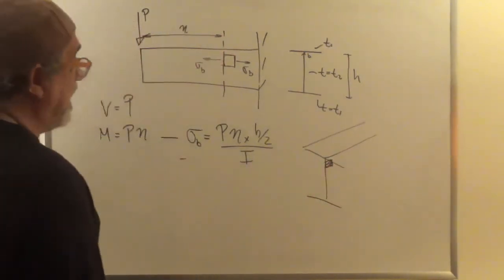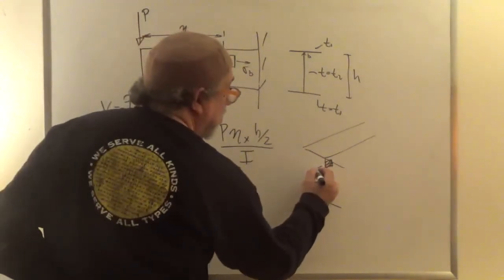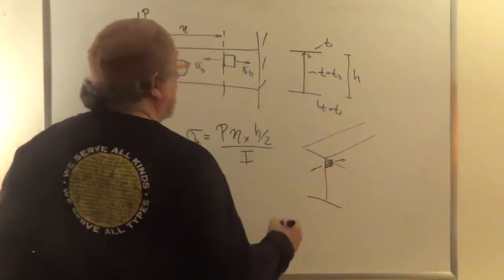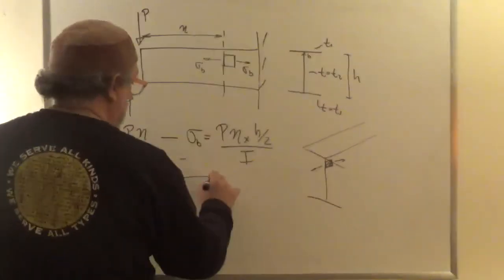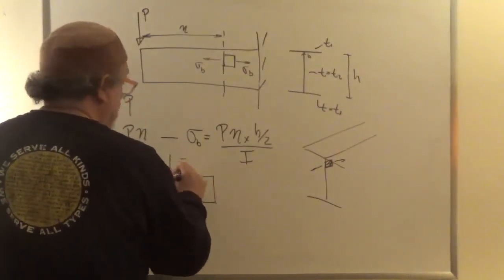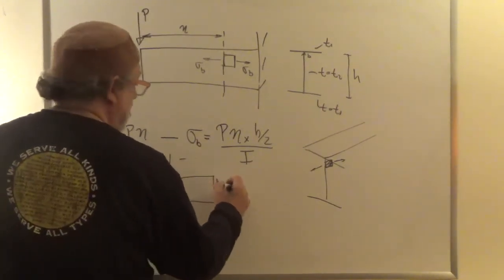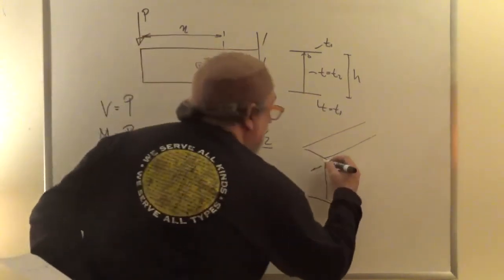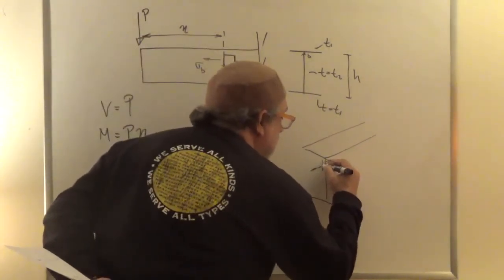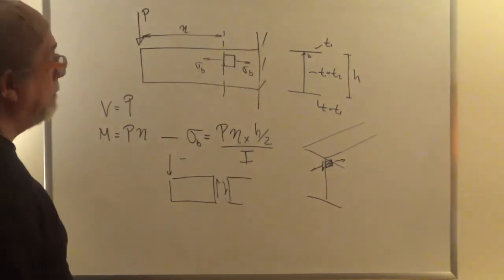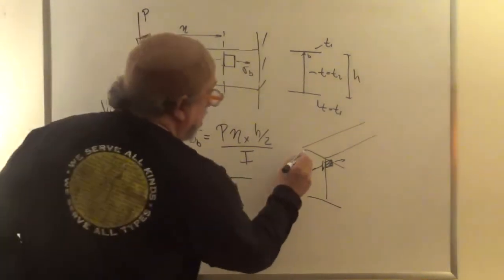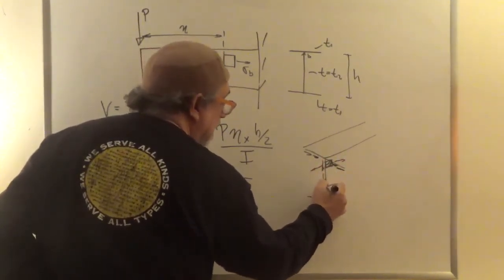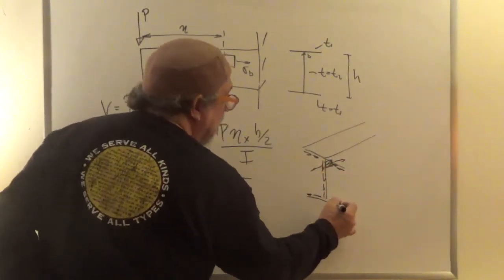That element is kind of like that there. It has the tension like this now. Okay? And when I looked at this part here, and I saw this, and I saw that, then I looked here, and this is down. So that means that here we have a shear stress that is down like that. Okay? From the shear flows, which are coming in like this, and then they head down this way, and then they head out this way.